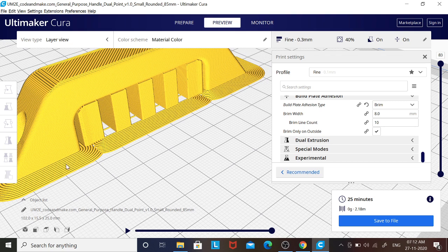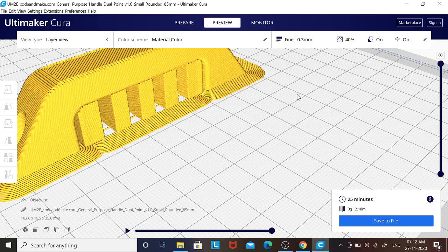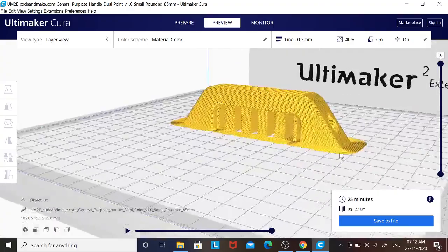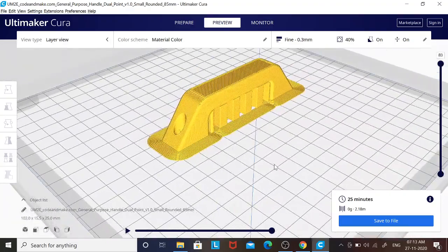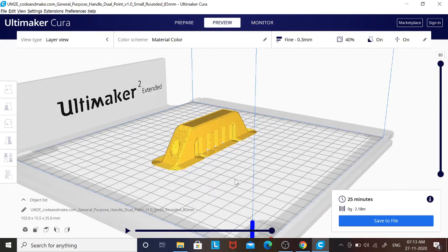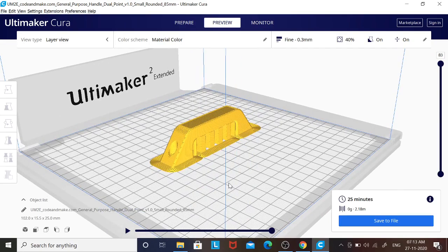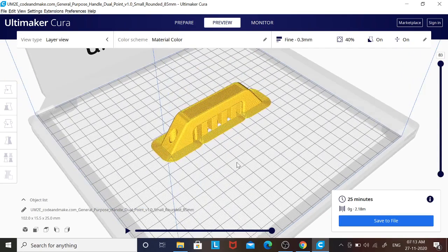Okay, so this is how you can just change the different orientations in your model and try to generate the optimum orientation where you can have fastest print with minimum support and minimum material. Okay, so that will be a task. Okay, unless and until you're happy with the orientation, don't go for the actual print. So yes, 3D printing is a time consuming job, but with a different orientation, with different settings, you will make sure that printing is perfectly optimal.